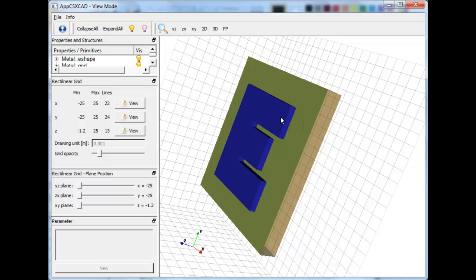What you see before you is the implementation of our MATLAB code provided as an OpenEMS structure form. As you gaze upon the structure in all its glory, you will see multiple layers. The top layer being the model for the E-shaped patch antenna structure, also known as the patch. The gray layer being the dielectric, which we had defined all of the properties for, all substrate properties, and the bottom layer being the ground.